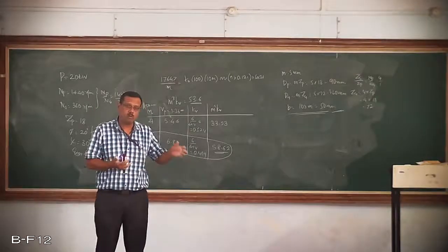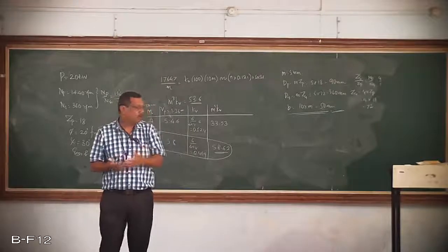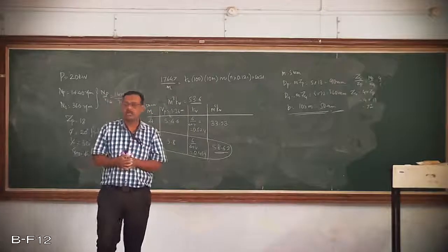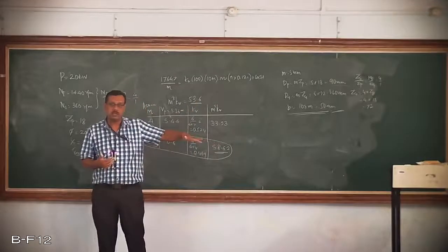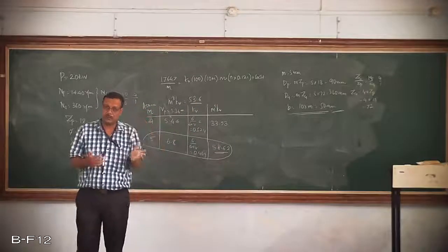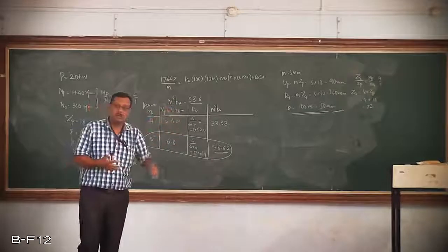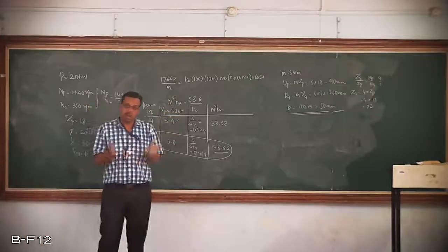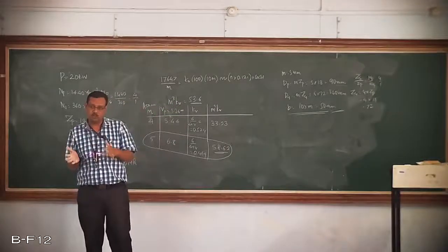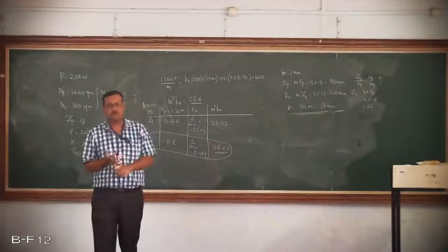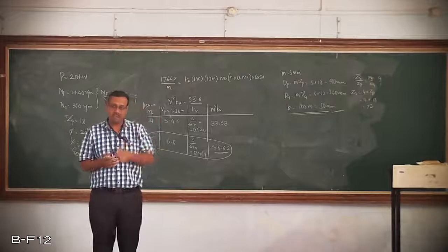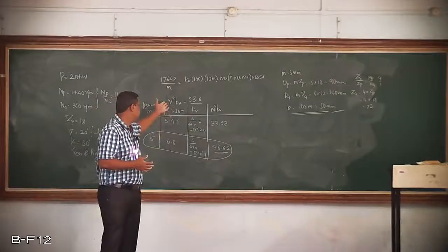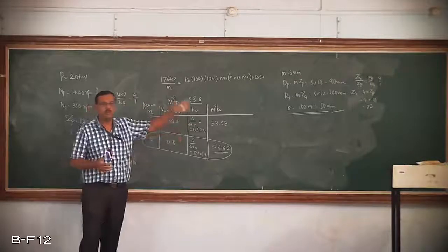That is the first problem we dealt with. The second problem dealt with the design of the helical gear where we have to determine the dimensions of the gear, not like the previous case where dimensions were given. Power transmitted is given. Material for both the gears is the same, therefore check which is the weaker part, then get its velocity, use the Lewis equation, and using it you can find the module and thereby calculate the dimensions.